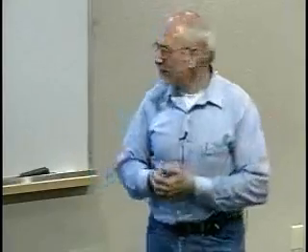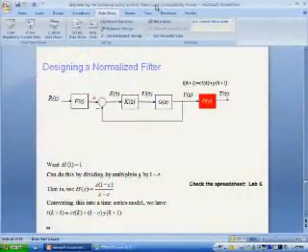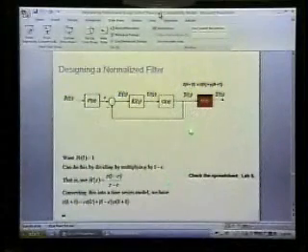So the problem is that we need to redesign that filter. Or we could readjust. That's a good point. We could either redesign the filter and make its steady state gain 1, or when we insert the filter, we also go back and adjust the precompensator. Either one will work. But for modularity purposes, I'm assuming we would prefer to localize our effects, plus it works better with the pedagogy. So what we're going to do is redesign it, and we can change it just a little bit.